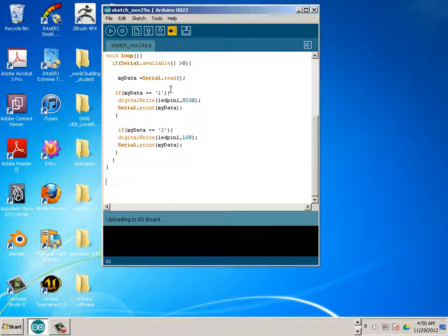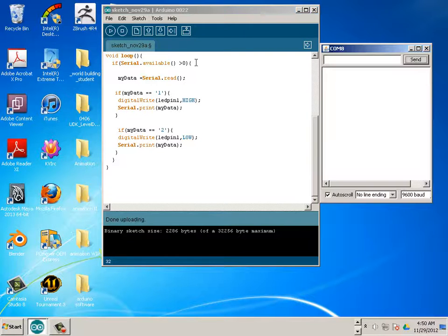Perfect. Let's throw it over to the Arduino unit. Now I'm just going to go to the serial monitor and type in 1. If it's 1 and hit enter, something should pop up. 2. Notice 3 and 4 do not yield anything. A 1 and a 2 equals 49 and 50. But a 3, a 4, or a 5 do not initialize anything. It doesn't spit out into the window.